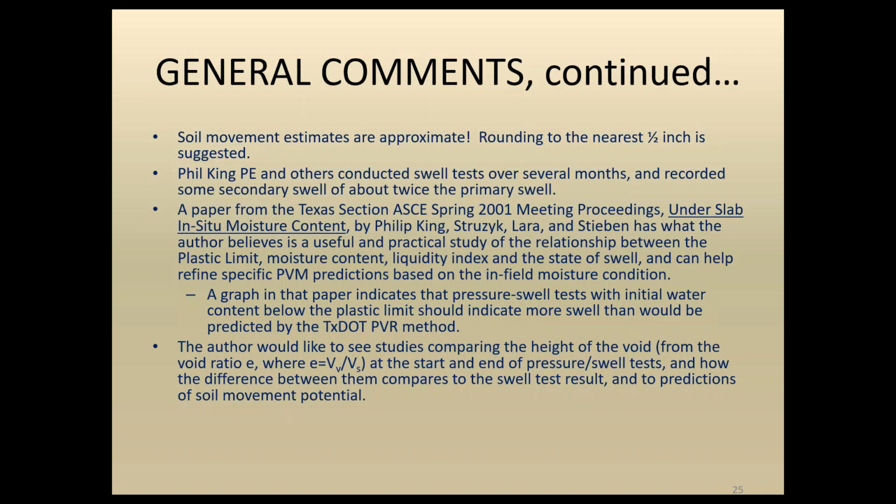Many of you know Phil King out of San Antonio. He and others conducted numerous swell tests when practicing in the San Antonio area, and they took some of the swell tests and went ahead and let them continue to swell over several months. And he said many of them had secondary swell of about twice the primary swell. And so that can be pretty disconcerting and difficult for consulting labs to actually have tests that ran months before we could give results. But worth some thought, in my opinion.